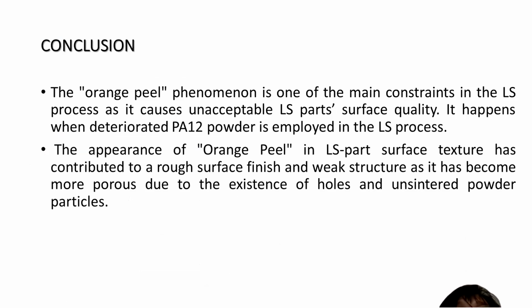Conclusion: the orange peel phenomenon is one of the main constraints in the LS process, or laser sintering process, as it causes unacceptable laser sintering part surface quality. It happens when deteriorated PA12 powder is employed in the laser sintering process.